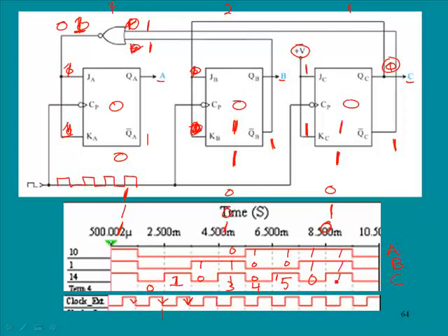Okay, now the next one is a critical count because we have to go from 7 and effectively reset to 0. Now, the way this is going to occur, notice this one will always toggle, so it will go to 0. Notice we have the 1 going over here to this, so this one is going to toggle. And since we have the 1 here and the 1 here on the B and the C outputs, the QB naught and the QC naught, again, they're at that 0 state. That is the only state that causes this to be enabled, so we have a 1 here.